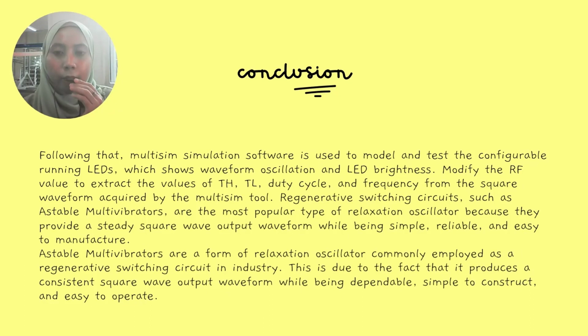Following that, Multisim simulation software is used to model and test the configurable running LEDs, ratios, waveform, oscillation, and LED brightness. Modify the RF value to extract the values of TH, TL, duty cycle, and frequency from the square waveform generated by the Multisim tool.